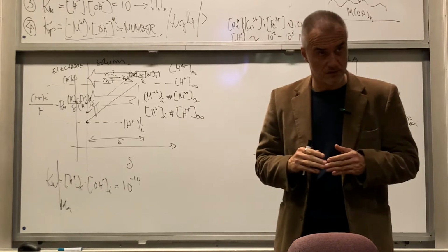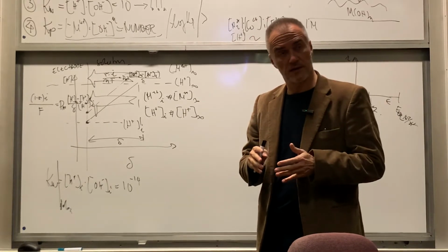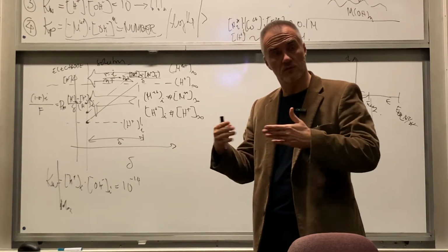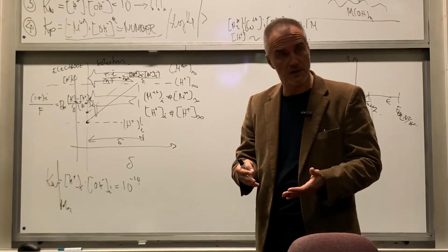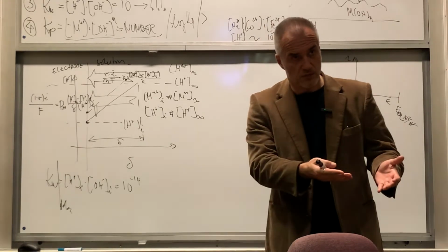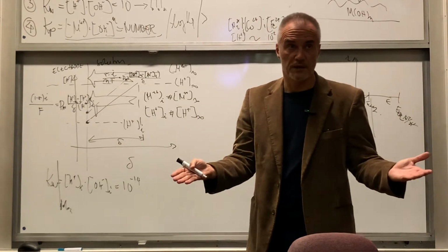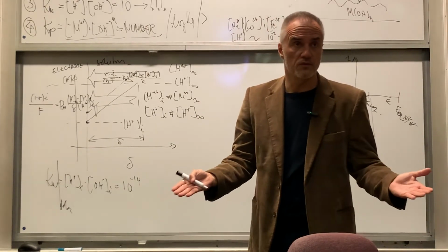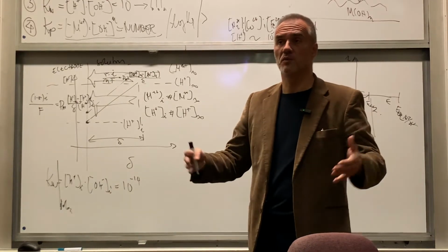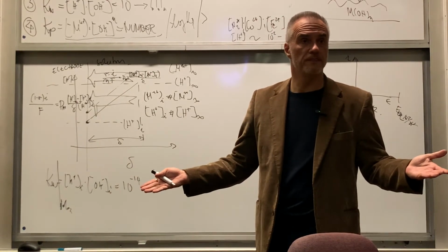If hydrogen is depleted first and starts to precipitate, because of that we precipitate hydroxide, I might grow my cobalt iron, which is going to have 30% of the oxide phase. That cobalt iron will not be good for any application because the magnetic moment will be disastrously low.